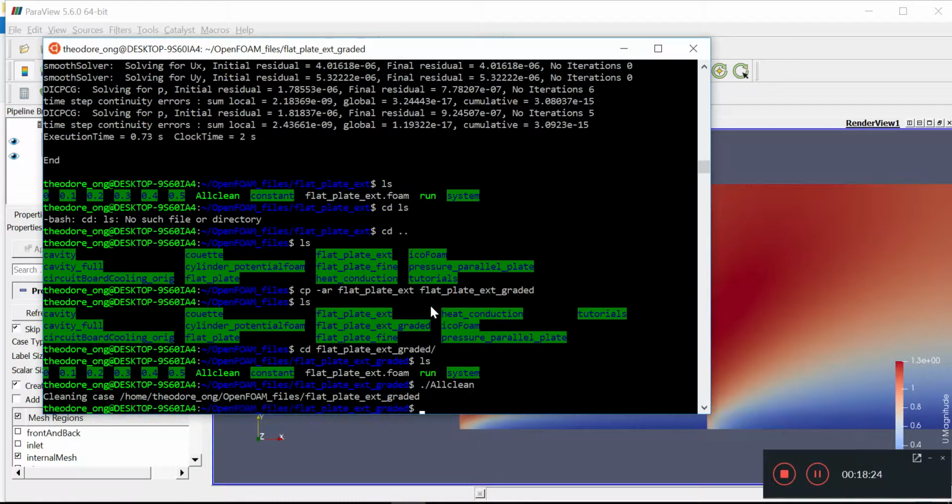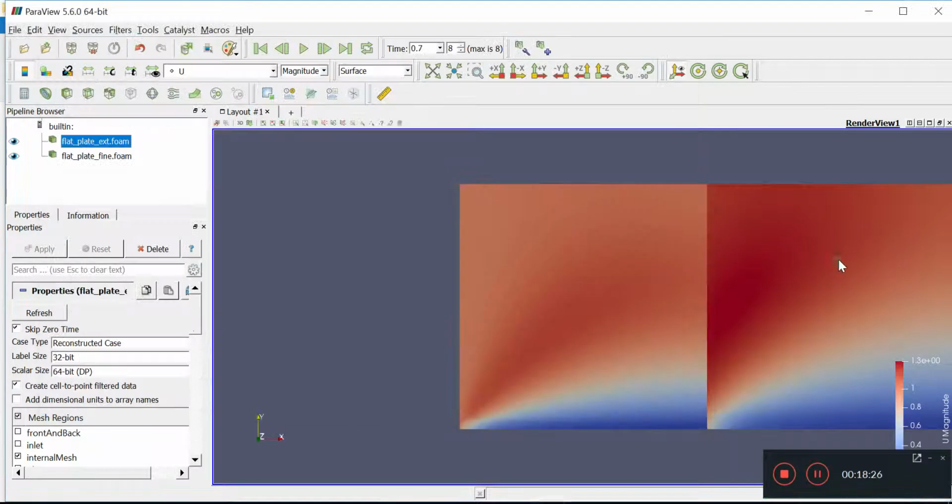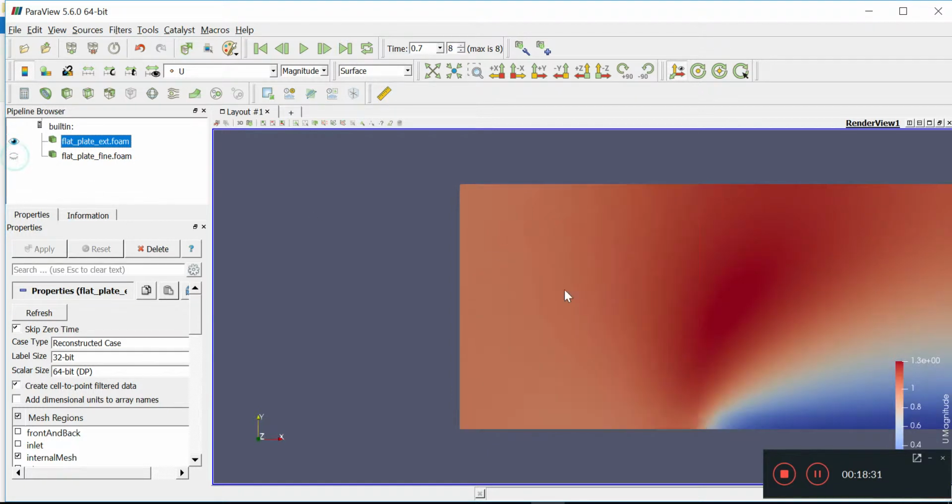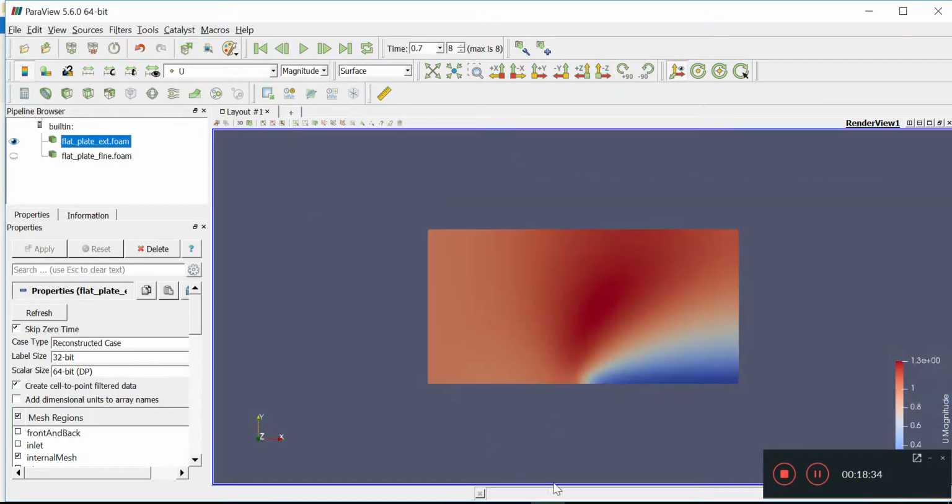Okay, but anyway, I think the best way is to just stop the video for now. Just let you know that we have successfully altered our geometry. At least that's the successful thing. We have this front part where the velocity is able to do its thing, become like a free stream. But you still see that you have this pressure buildup in here, and the velocity here is faster than 1. Even if you look at the x magnitude, it's still not quite right, and we are probably wondering why.